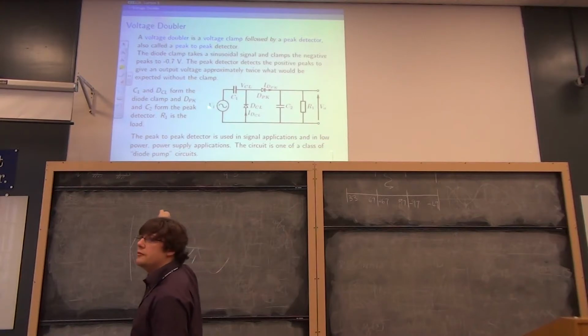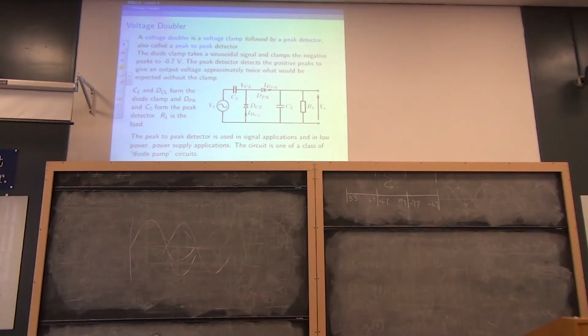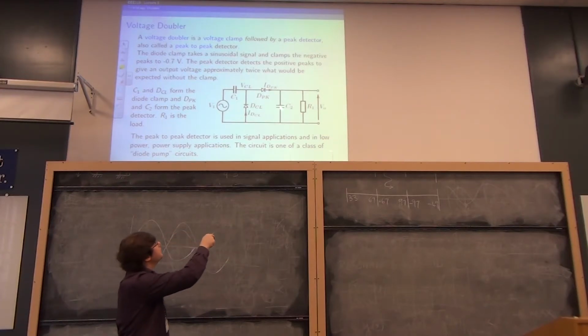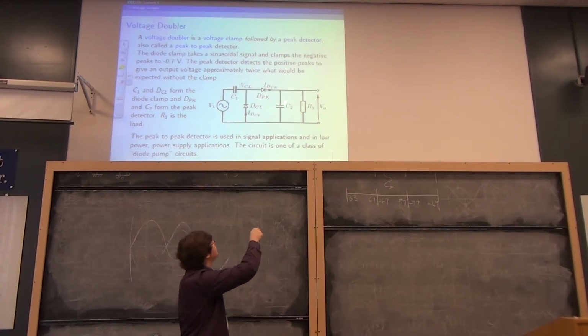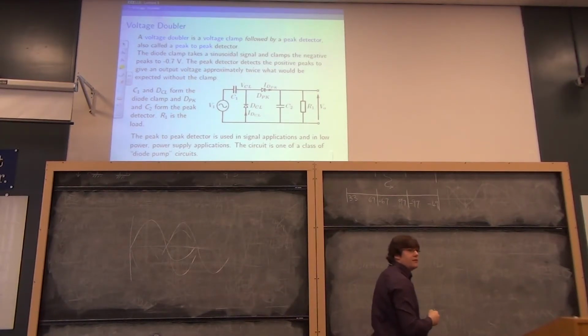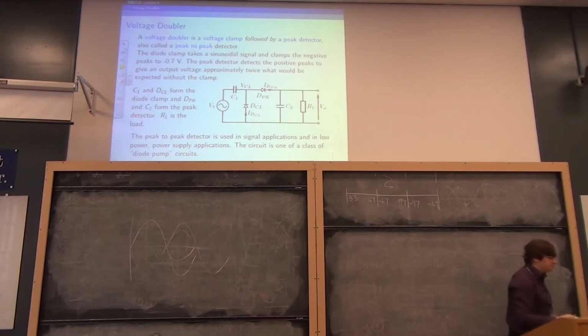It's not adding any energy to the capacitor. Consequently, all the energy we've got is available in here. And then this peak detector diode turns on, and this energy is taken from here and passed into C2. And then it immediately starts to discharge through R1. So there's a finite amount of energy available for this transfer. It's a sort of charge pumping action.